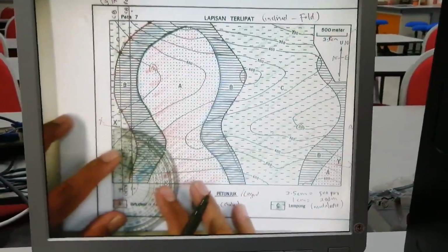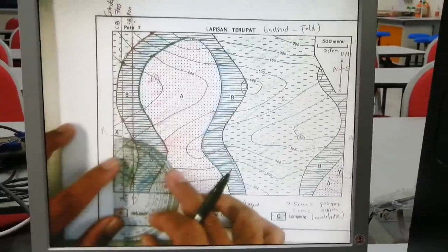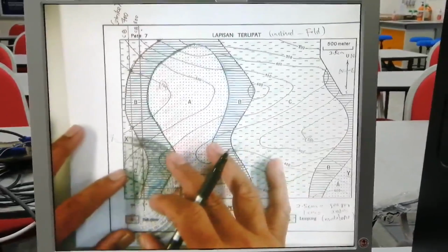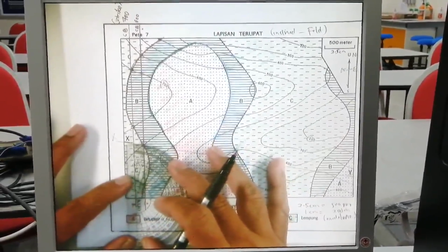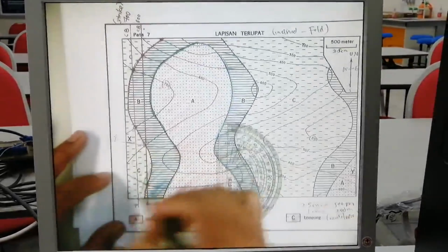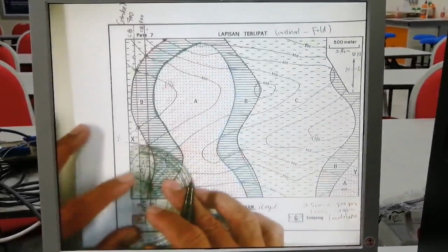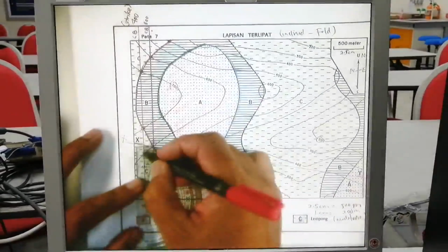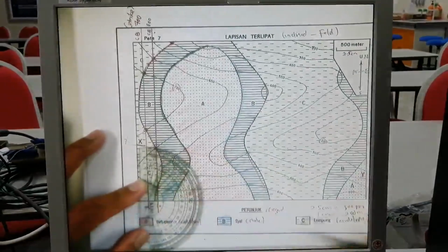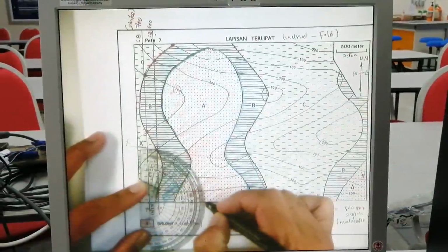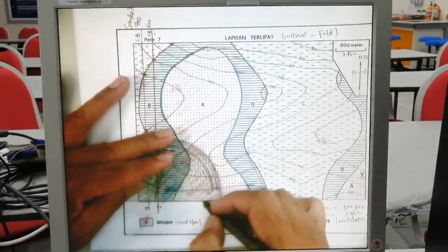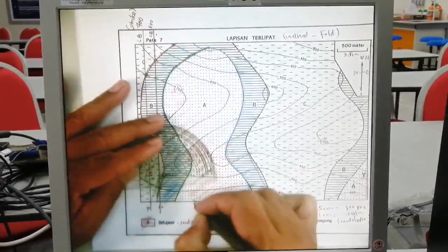The angle to the protractor must be 90 degrees. Put your protractor from 0 here. You must center it on this line point here, so your center must be here, and your straight line must be parallel to the 0 to 180 degrees line. Then make sure you're here, and it must be 90 degrees. So my 90 degrees here looks like this line is perpendicular to this black line.